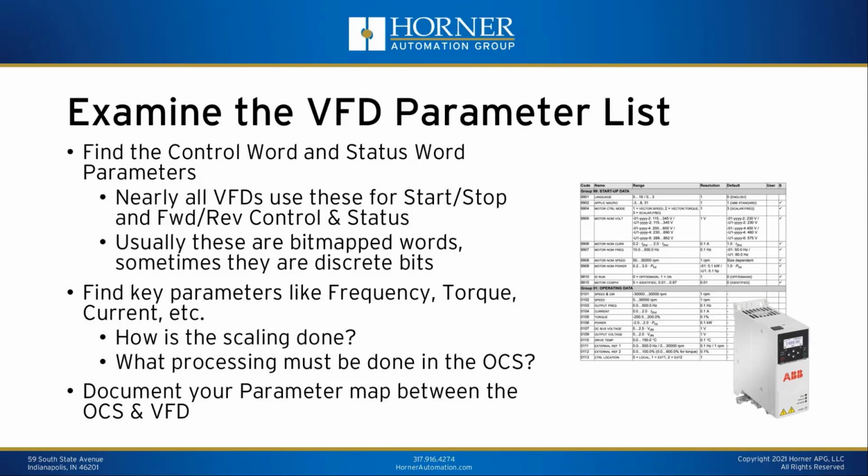with the drive. Whether that means you're strictly adjusting frequency over the network or whether you're just monitoring parameters or faults, whatever the case may be, the drive is going to have a whole host of parameters that are accessible, and usually a bulk of them are accessible over the network. So you're going to want to be familiar with A, what parameters you care about for the application, and B, which parameters you may want to occasionally access, maybe from an operator interface screen, as opposed to parameters that you're going to want to monitor and or change on a live, real-time basis.